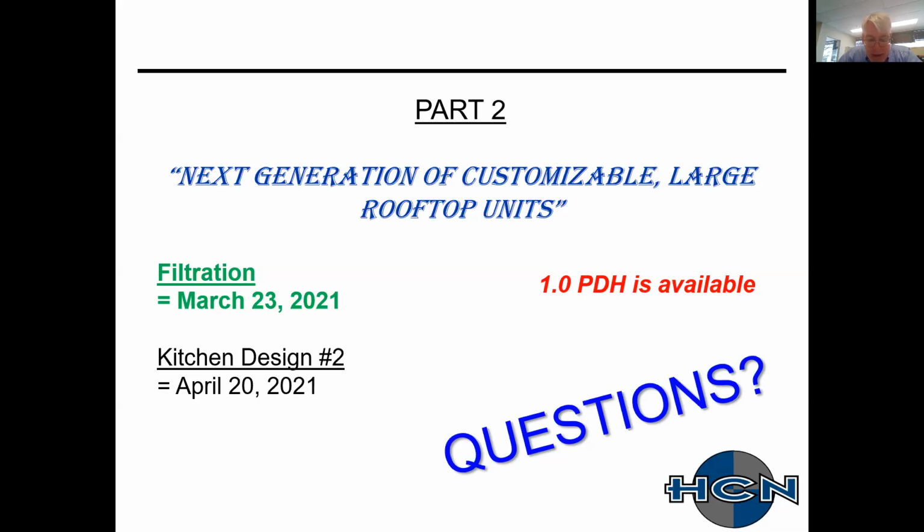The other thing to consider is that there are so many different components and systems available with hot gas reheat: compressors, whether on-off or now two-stage digital scroll and VFDs, different coil components, aluminum, copper, as well as aluminum microchannel, as well as the controls.